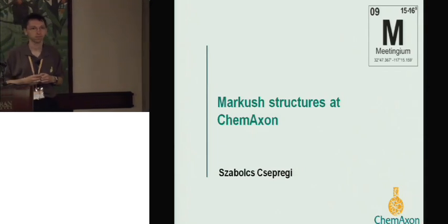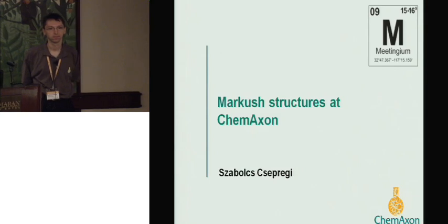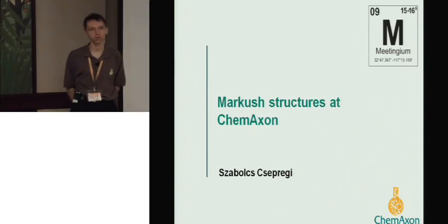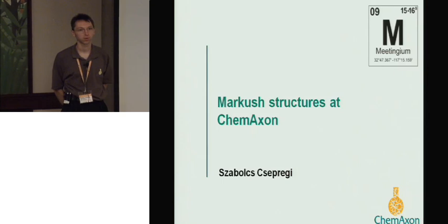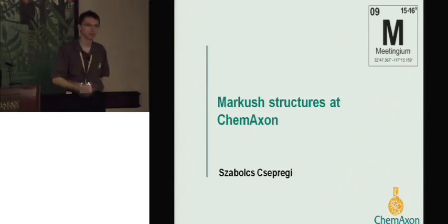And I guess one other comment, just in case people aren't aware, which we discussed, is that if you have an any table and you put a Markush structure in it, it's not actually going to be treated as a Markush structure. That's just something to be aware of. No, it will be treated as a fragment, as a collection of fragments. It needs to be actually created as a Markush table. You need to create Markush tables to allow this capability.